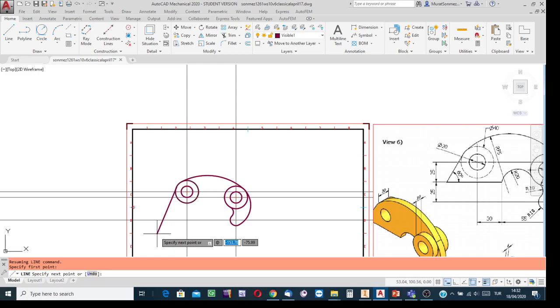For instance, write the length of the line as equal to 130 or 200 or even more. Okay, and then if within the following box there were a degree or angle symbol, then I would click on the tab key to take a right to write the angle. But here you see there is no degree symbol, so the third trick comes into play.